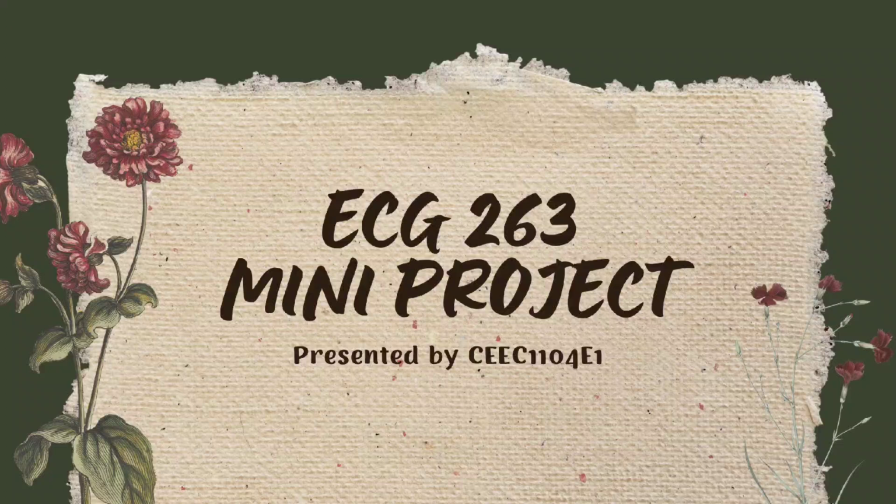The findings of the compaction test were very helpful. The maximum dry density obtained from the laboratory test was 1.947 gram per centimeter cube, and the optimum moisture content was determined to be 10%. Comparing these values with the field density results, the relative compaction was calculated to be approximately 95%, which falls within the typical required range of 90 to 95%. This indicates that the soil has been compacted adequately in the field, but there is still some room for improvement.